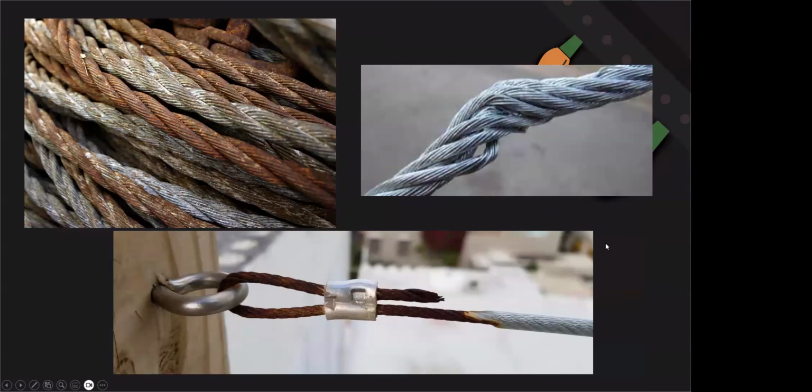But something people forget about is condition. That is perfect condition cable, brand new, out of the box, no corrosion. You can see on here the corrosion narrows this down pretty quickly, rust all over. Over here, I've used this three years in a row, and when I put it away, it kinks a little bit. Every little kink like this takes away capacity from the wire. The rust reduces the area, so it doesn't work quite as well.